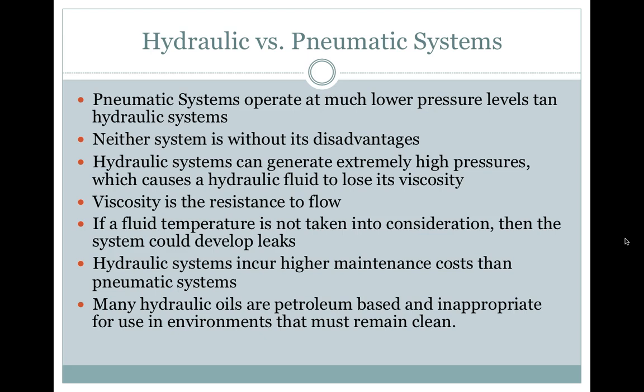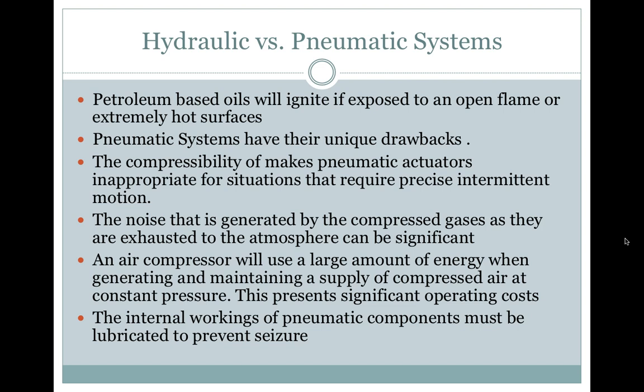Hydraulic systems can generate extremely high pressures, which cause a hydraulic fluid to lose its viscosity. Viscosity is the resistance to flow. If a fluid temperature is not taken into consideration, then the system could develop leaks. Hydraulic systems incur higher maintenance costs than pneumatic systems. Many hydraulic oils are petroleum-based and inappropriate for use in environments that must remain clean. Petroleum-based oils will ignite if exposed to an open flame or extremely hot surfaces.